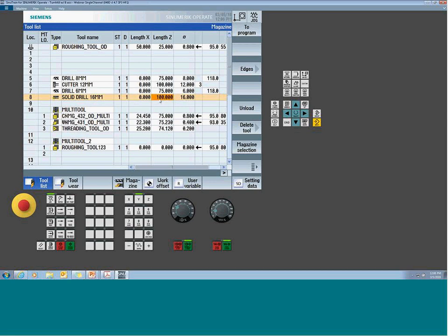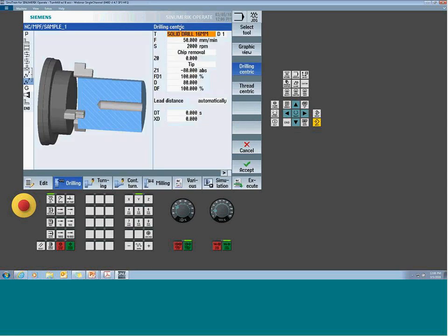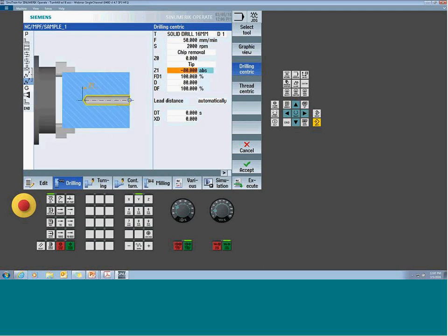Standard drill. So enter the projection from the spindle face out to the tool tip. It's centric. So in the centric cycle, it can only ever allow this to drill at a B0 or B180 location. So we don't have the ability of flipping to a peripheral surface or anything because of the nature of centric: it's spinning the spindle, and the tool is being held stationary. So fill out the rest of the cycle as normal. How deep am I going? If I want to use peck, what would my max peck be? I'm taking it all in one shot.